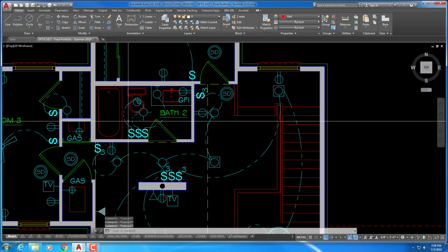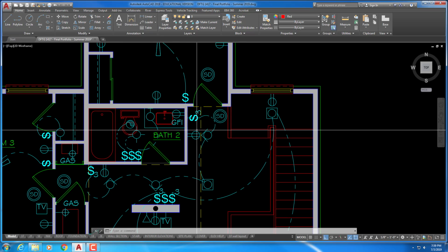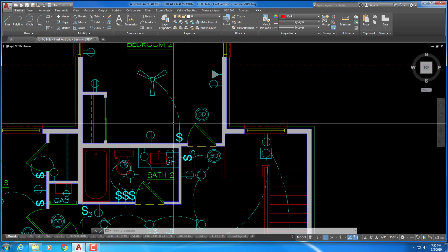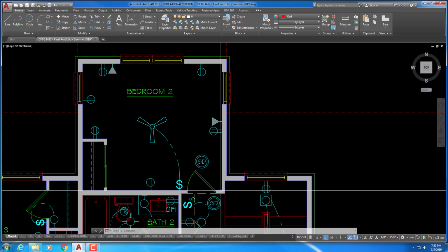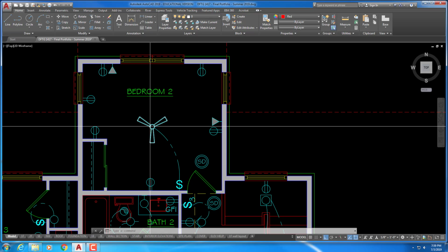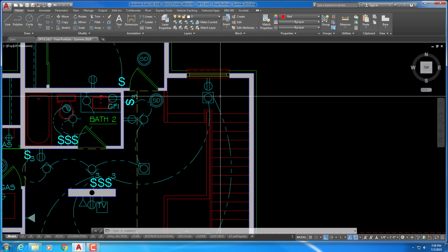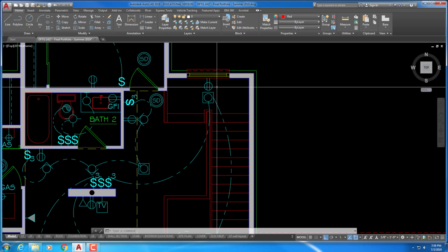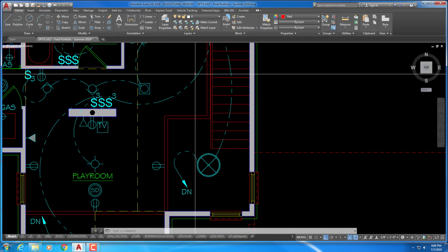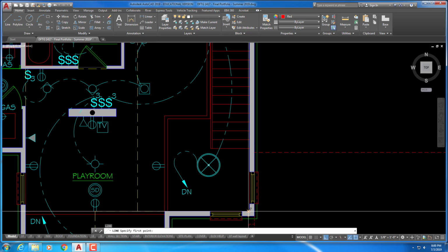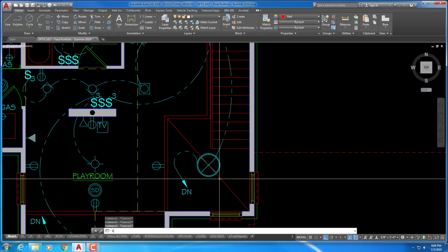And then we've got a vent, a light, again 0.5, 0.5, this is 1.0 here, GFI, sconce here, S3 switch here, smoke detectors, typical. This light, take the diagonal in this room from this corner to that corner to find the center line, the midpoint for that. Then this is not technically centered. I moved this over slightly so you could see the plug. I guess you could center it, but not really necessary. It needs to be over the landing though. And this one is centered based on here to there. So that's the midpoint of that line.